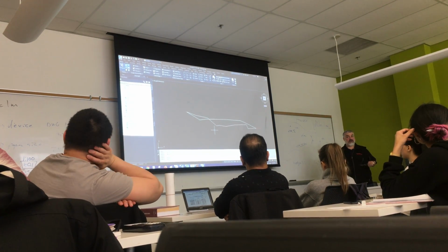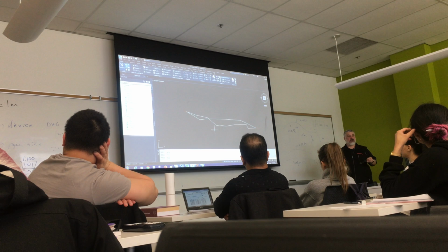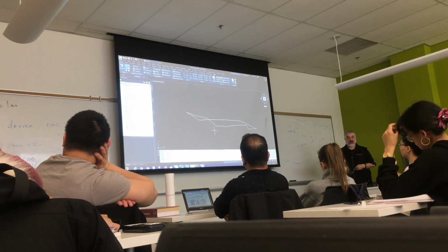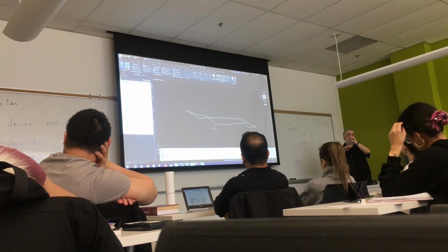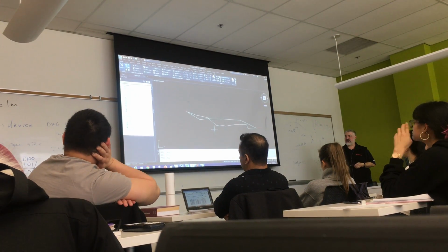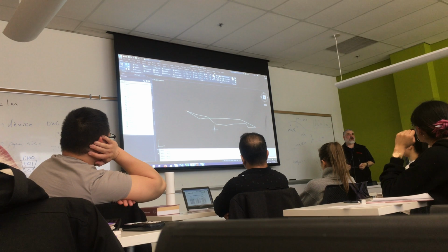Okay. Remember not to include your construction material. Right? That's not native earth. Right? It's not native material. You shape your subgrade and then you bring your construction materials in to go to the finished ground. So you design it to finish, but then you build it to the subgrade first, and then you bring in your construction materials. Any questions so far?